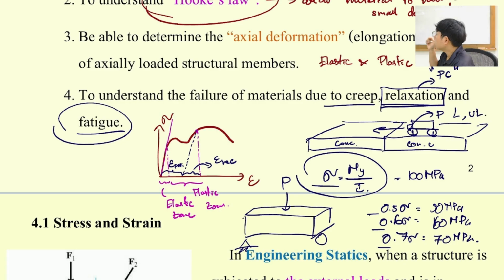Okay, which means when it steps on our concrete surface, it's going to load, and when the vehicle passes, it's unloading. So when I test at 0.5, I allow P to have just 0.5 of the stress, and then I put the force here and release. I put the force here and I release. After that, I'm going to count the cycles. Okay.